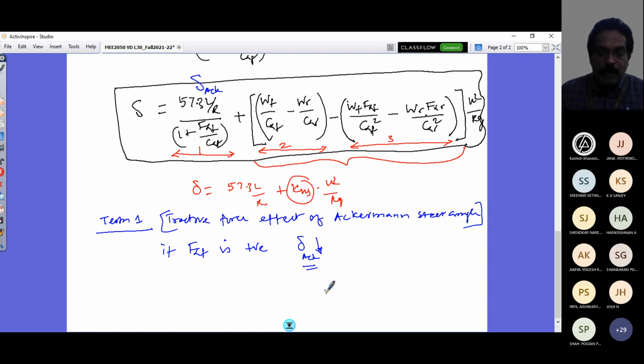And that would account for the sense that the forward wheel drive pulls the vehicle around in a low speed maneuver. Correct? Ackermann steering geometry is what we have looked at in low speed cornering, and it pulls the vehicle around in low speed maneuvers. That's the meaning.